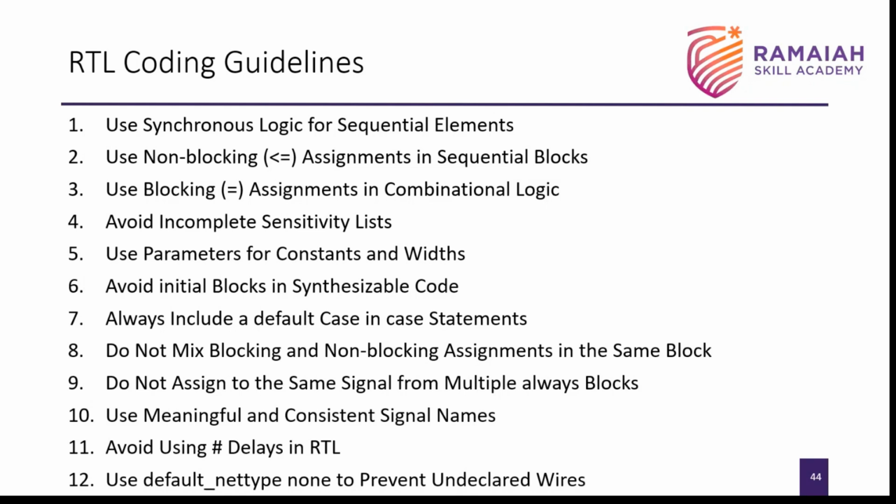And for every case statement, we should always include a default case. Suppose I have used the select lines from 0, 0, 0 to 1, 1, 0, that is 6, and I have not used the value 1, 1, 1. The tool doesn't know what output it should give for the select line 1, 1, 1, so it will show some error.